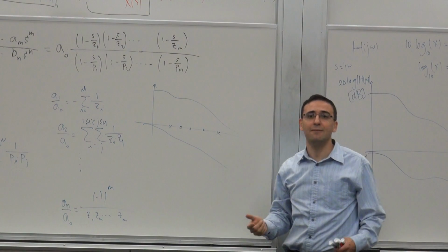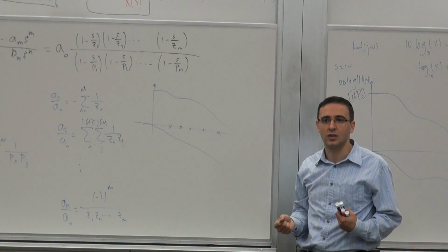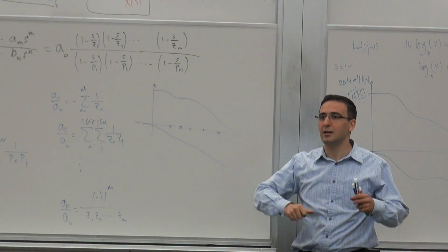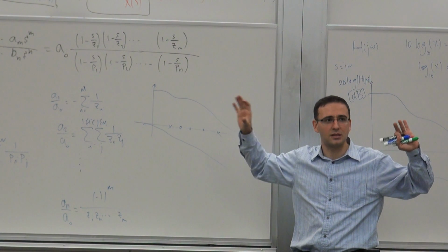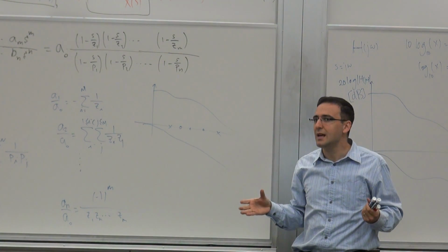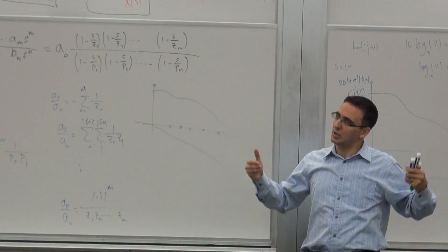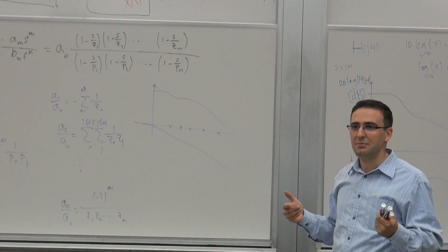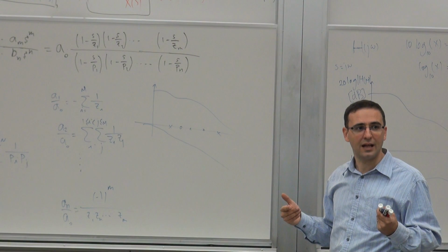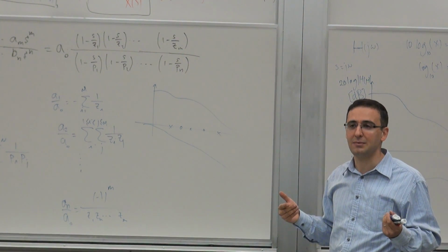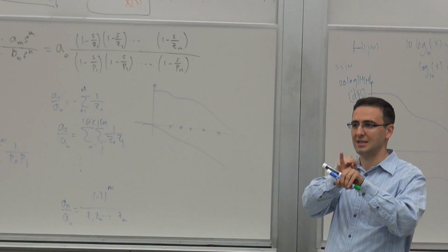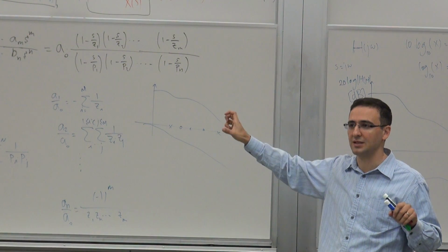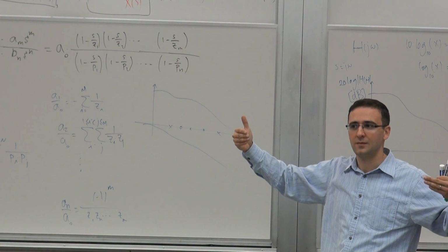Now, but not every amplifier is like that, right? We saw another example when we were developing that discrete design example that we did a couple of lectures ago. In that case, we had coupling capacitors and bypass capacitors, right? Which basically made the gain very small at low frequencies. Basically, at DC, it made the gain zero because the input was detached from the amplifier and the output was detached from the amplifier through a capacitor.